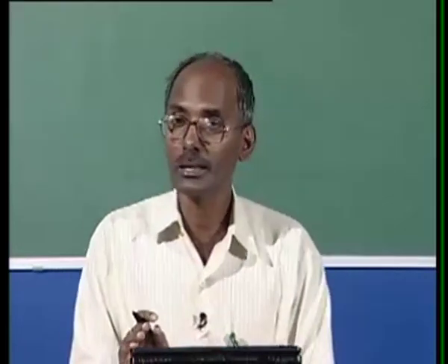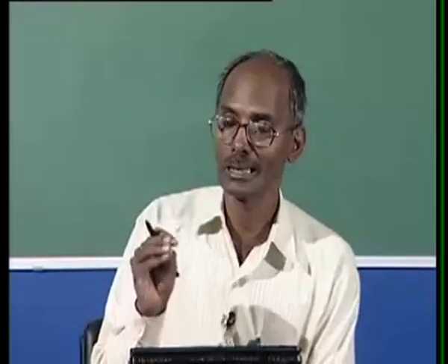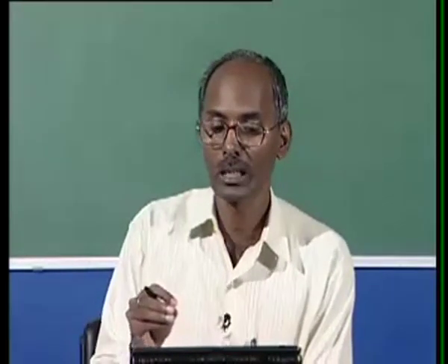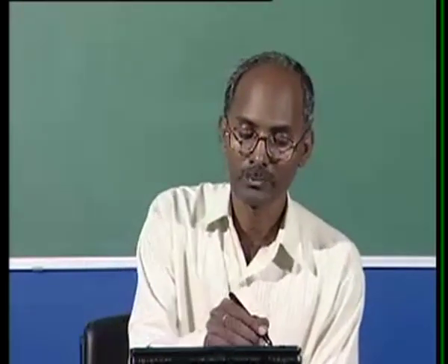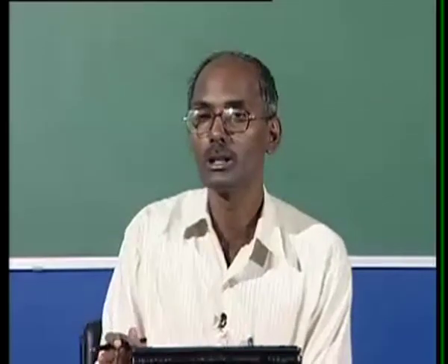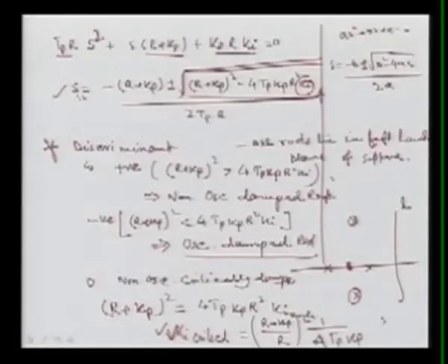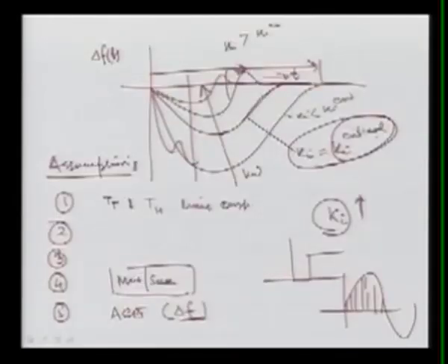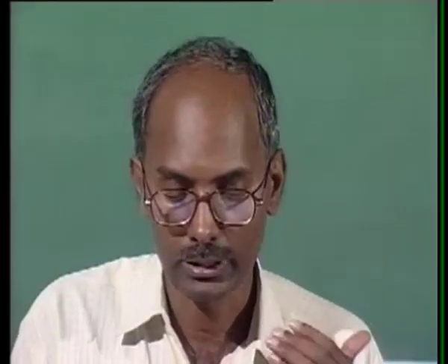But in all the cases we found that if we use the integral controller, it is reset control, it is reducing our frequency error. At the same time, we can see from this equation that it is a stable closed-loop control, and we also verified from this graph that it is stable. We made various assumptions, and we justified them, so that is how it is true.